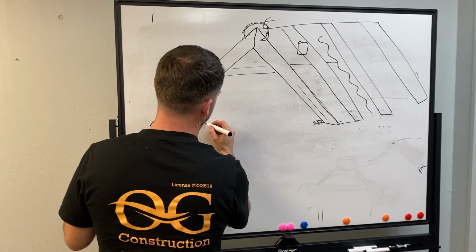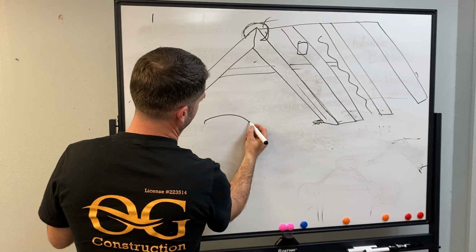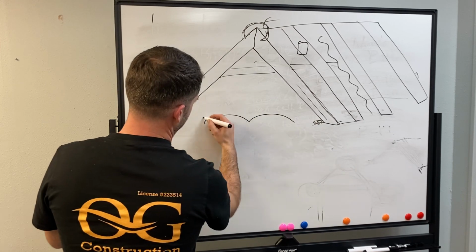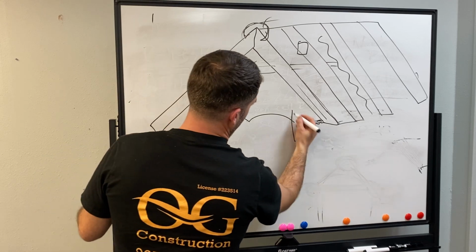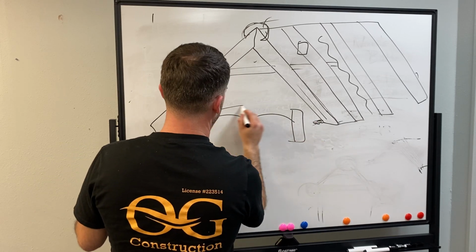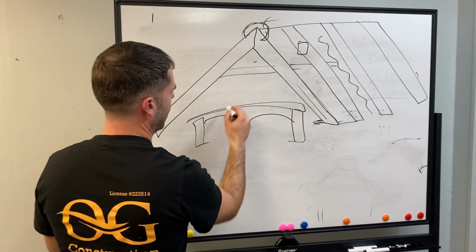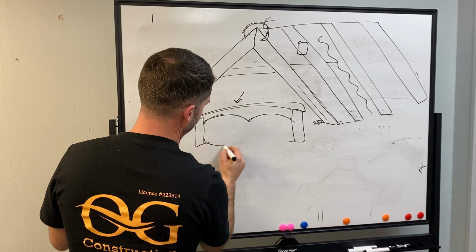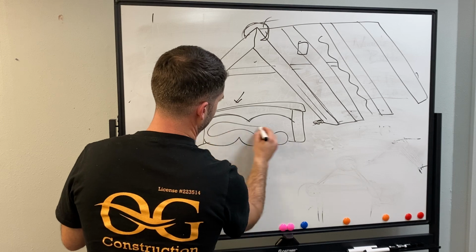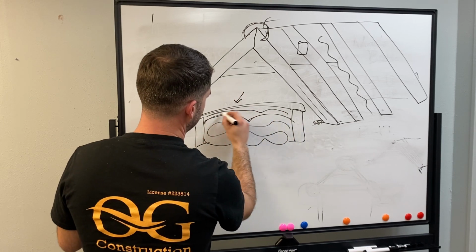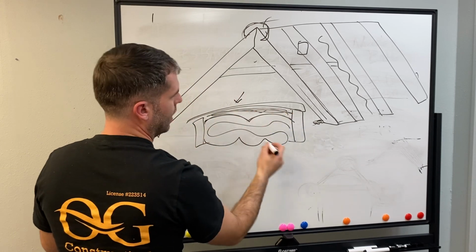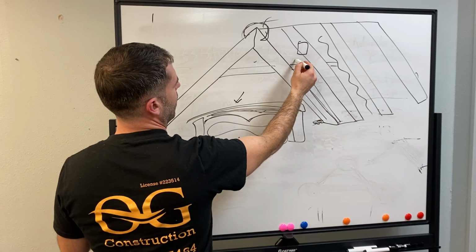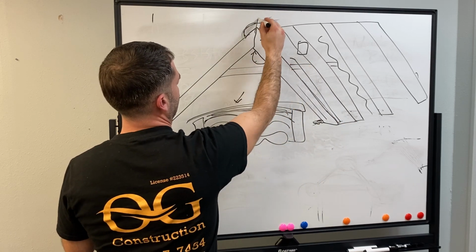So what they have is these little plastic foam baffles that look like this. If your rafter's right here, and this is your sheeting, your plywood, this will go in here as a breather, and then your insulation goes right here. You have to make sure that air can come through here, and it goes all the way up, and then it expands right here and goes out.